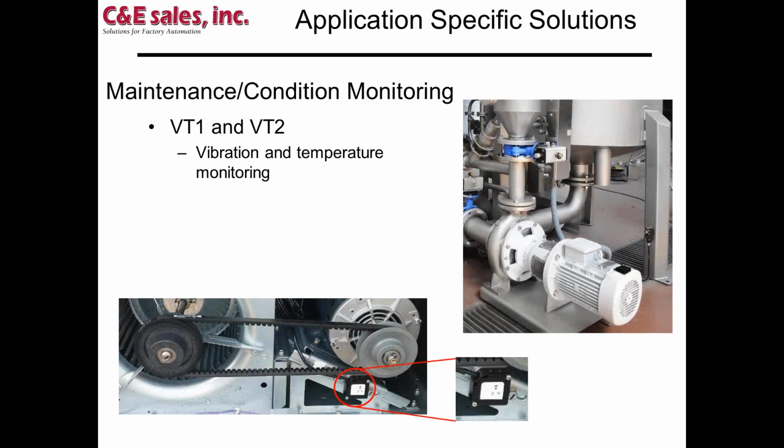So basically, there are some rules of thumb for this. There's actually a published document of different vibration levels, but what I found is that you need to go in and take a baseline. Where is it performing today with everything known good? And then trigger some alarm or some light if you exceed that vibration level.